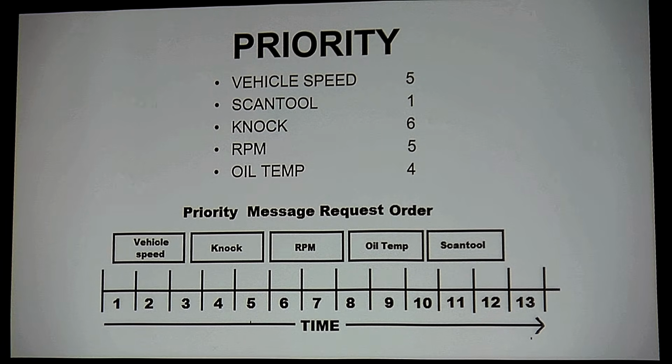Guys, there's so much latency between these points that I'm getting back off of any bus system. You've got to understand the latency that you have in scan tools. It's huge. If you think you're going to find some fast-acting problem with a scan tool, you are making a drastic mistake. You need to understand the limitations of your tools. Scan tools have latency, and depending on how much the bus is active is how long your latency is. So in this case, you can start to see that the CAN transceiver organized the data, and then this organized data is going to be stacked, and then it's going to go out as it comes in.